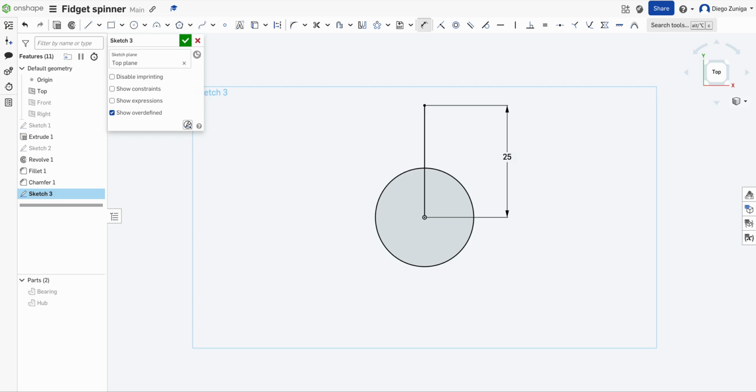So in order to use a line that we're not gonna use, we mark it as a construction line. I'm gonna click this, select the line that we just created, and make it into a construction line. Now it's a dotted line. And again, it's not gonna turn into anything once we do a 3D model out of it.